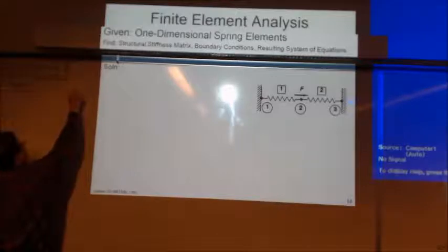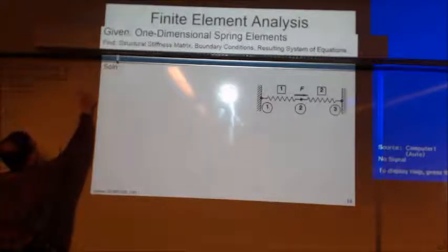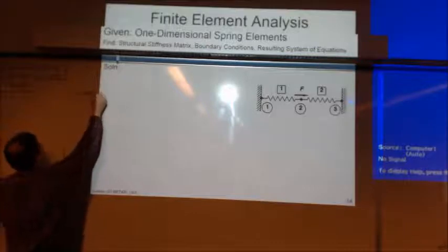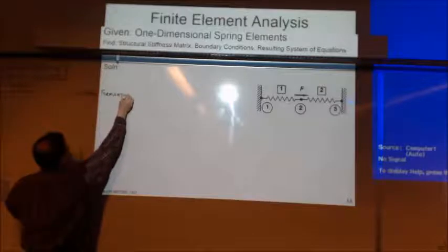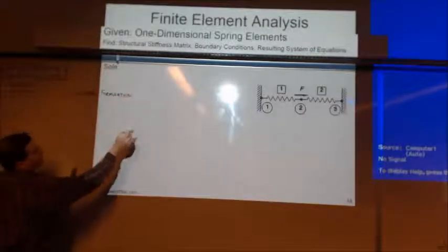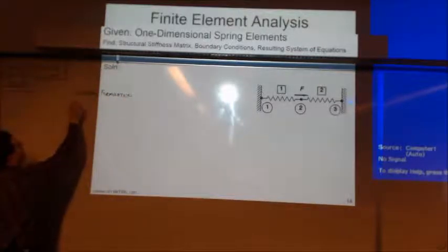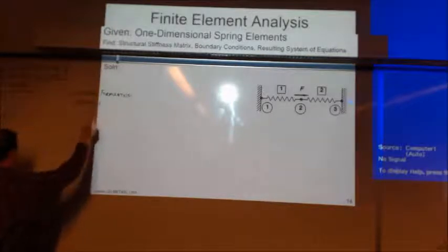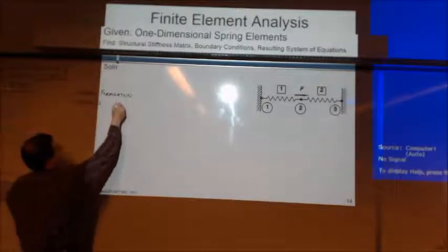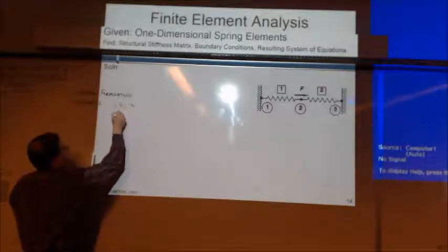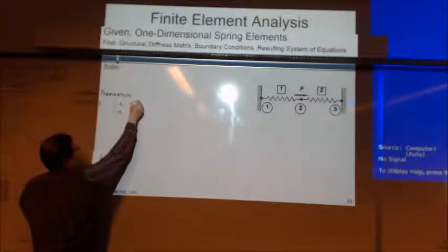So let's do our general formulation, right? For element 1, what's our general formulation? It's K1, minus K1, minus K1, plus K1, right?